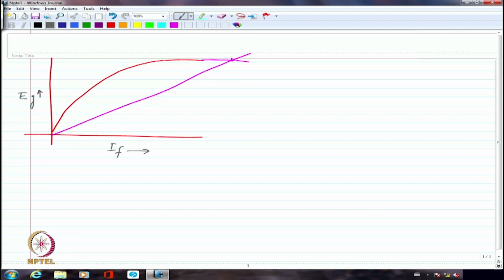And then when I plotted external characteristics, I should have taken the VT, which is actually not EG, it is the voltage across the field winding. So what we plotted yesterday was internal characteristics. Internal characteristics talks about EG versus IA. IA is the armature current, which is the internal current, and EG is the internally generated voltage, right?